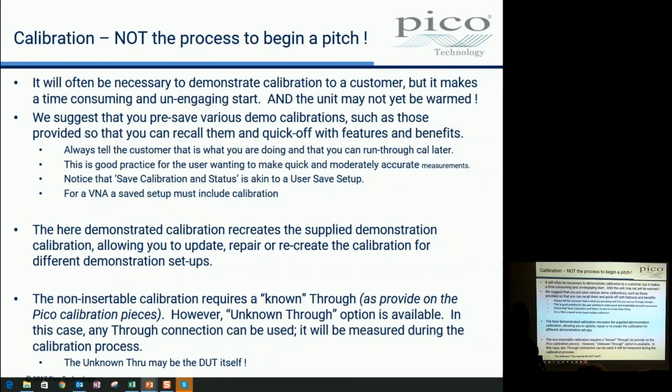It'll often be necessary to demonstrate the calibration to the customer, but it makes a time-consuming start, and the unit is not yet warmed. That's a really bad idea. You really do have about 20 minutes. It's not an hour to warm these things up, but about 20 minutes. And you can demonstrate the user interface and make some demo measurements before, and have a nice warm instrument to do your cal if you have to. Always tell the customer that that is what you're going to do, that you're recalling a calibration that you did earlier, or that Paul did earlier, and that you'll do a calibration later on.